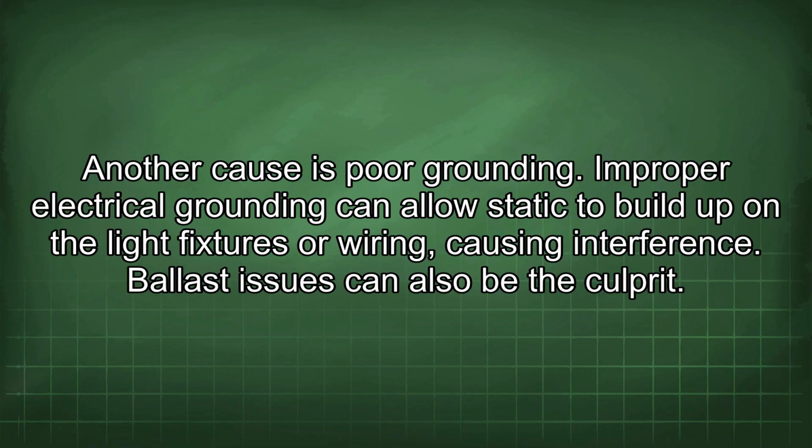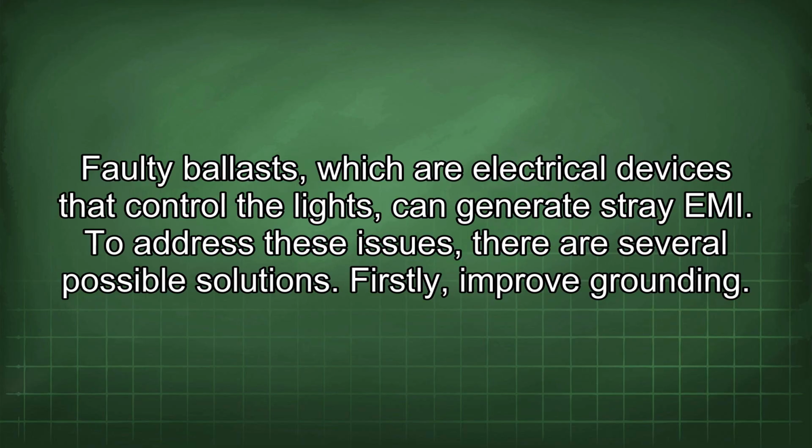Another cause is poor grounding. Improper electrical grounding can allow static to build up on the light fixtures or wiring, causing interference. Ballast issues can also be the culprit. Faulty ballasts, which are electrical devices that control the lights, can generate stray EMI.